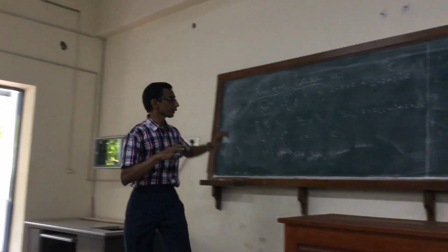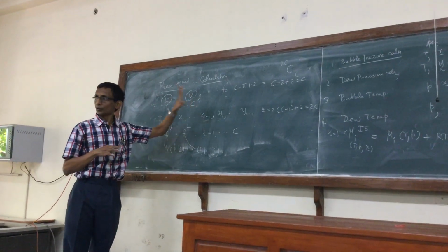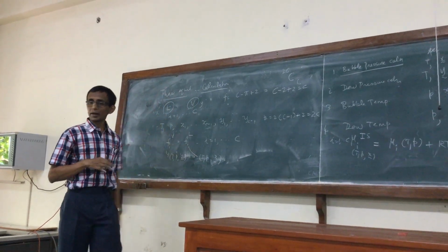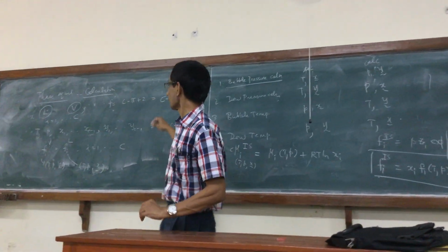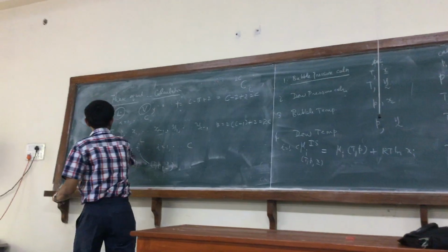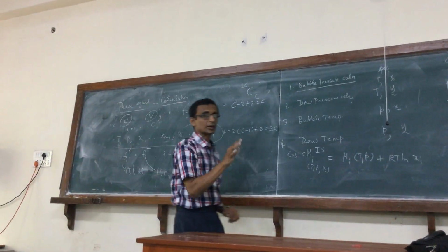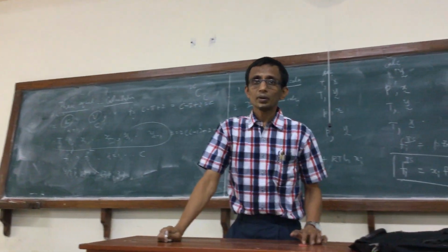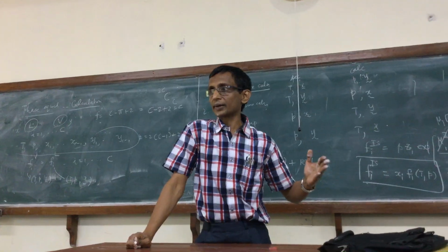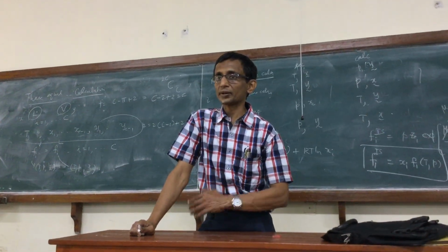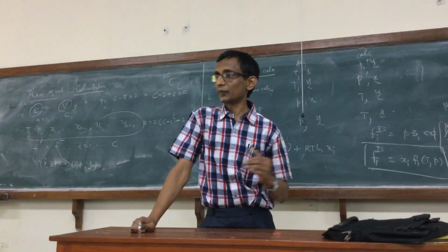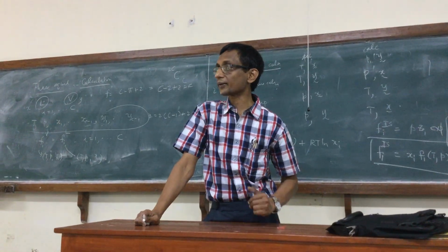While looking at the specification, it's better to ignore them rather than including 2 variables and adding 2 equations. At the outset, in the phase rule, typically they are not taken into account. But in calculation, the way it is constructed, those variables, the non-independent mole fractions, appear explicitly, and we account for that with the mole fraction constraint equations.